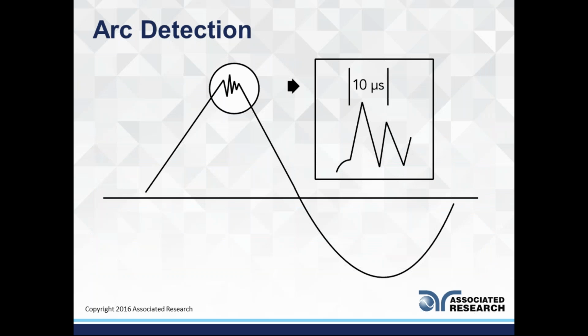Once we see breakdown, obviously your high voltage is shut off on your instruments, but that's a way to think about it. So arc detection: here you have your low frequency wave. Arcing is usually caused at peaks, obviously at high voltage. When the voltage is at its highest, you start getting these spikes, these high frequency peaks caused by the ionization of those molecules, or the proper terminology is corona.